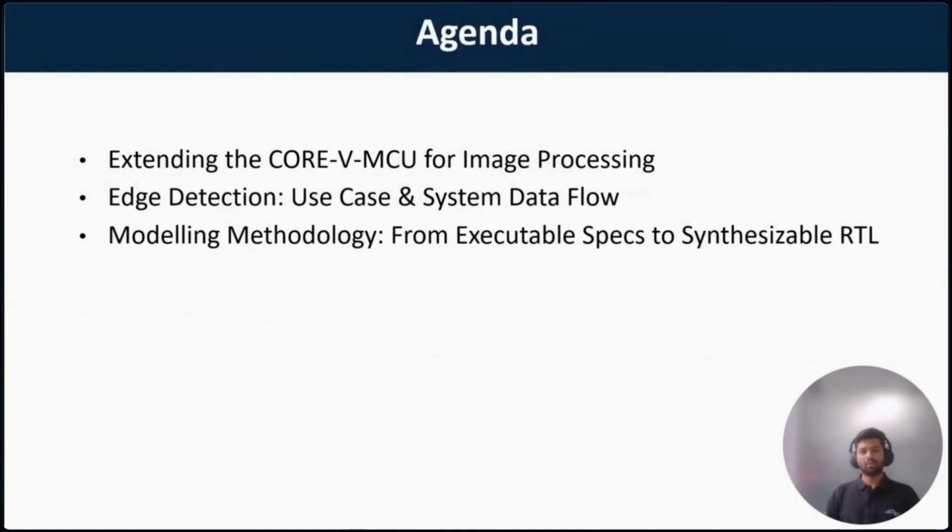We will start by looking at how we extend the Core EMC for edge detection, followed by an architecture overview. We then will dive into the use case and data flow, specifically how we implemented the image pipeline using the micro DMA and eFPGA subsystems. We'll see all this running in a demo.